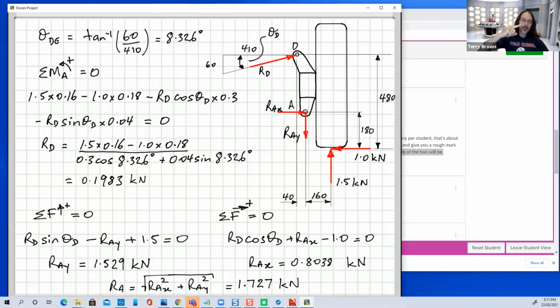So what you draw on this one are the forces that this one exerts on my right hand. And then when you draw a free body diagram of this one, you show what this body is exerting on this body. So we started from this free body because this is where our loads were. So we can't calculate anything anywhere else. We've got to have some input values to start doing some calculations. So these forces here enable us to calculate these reaction forces that are generated by this thing being pin connected